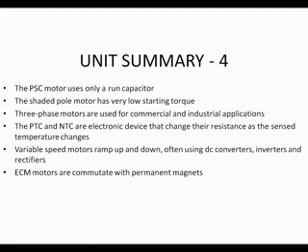Capacitor-start motors use start capacitors to increase the starting torque of the motor. The start winding and start capacitor are removed from the circuit after the motor starts. Capacitor-start and capacitor-run motors use both start and run capacitors. Run capacitors help increase the motor's running efficiency. The PSC motor uses only a run capacitor. The shaded pole motor has no capacitors, no start winding, and a very low starting torque.